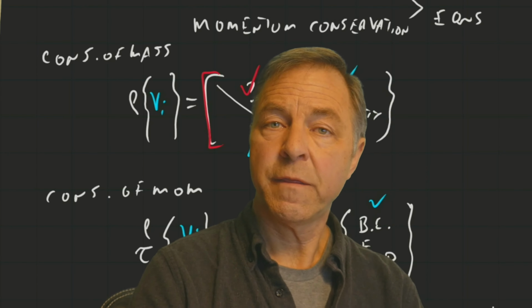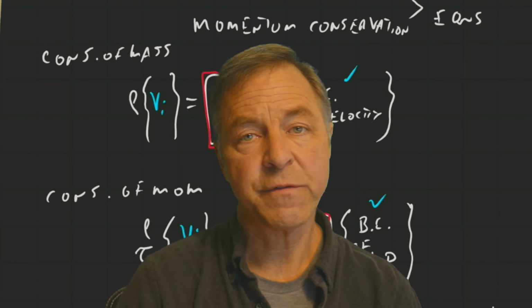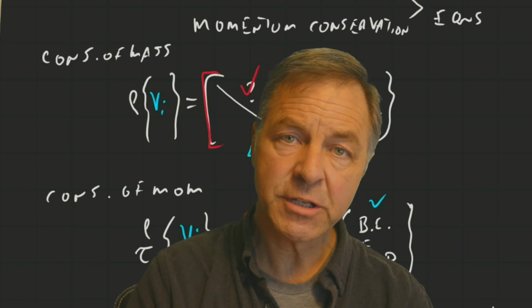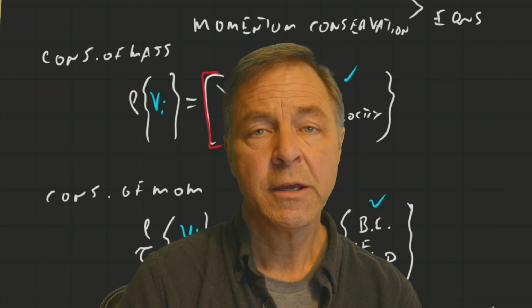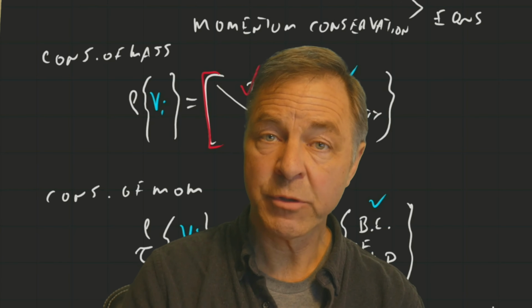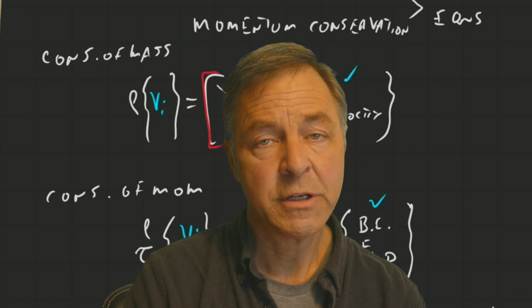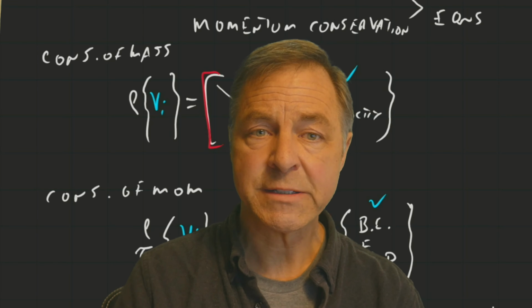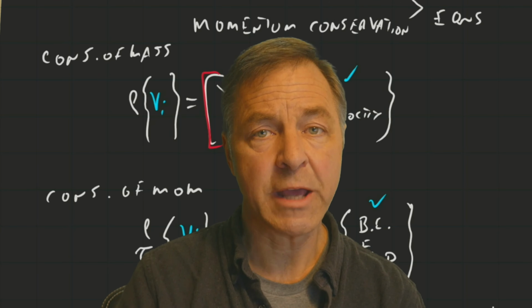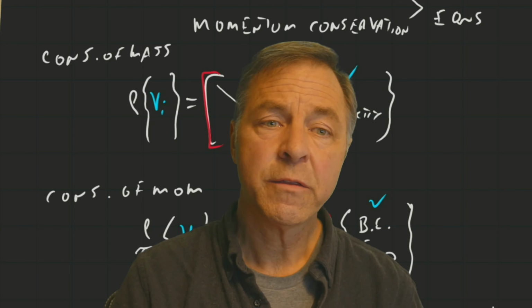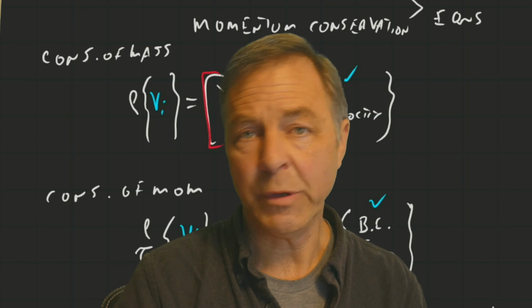So that's important. We've refined the grid size, especially close to the boundary layer where all the action is happening, frankly. In the case of an airfoil, the boundary layer is what creates the lift. So we need to have a grid that allows the modeling of the boundary layer to happen correctly. But then there's also the large-scale bulk flow that we can't ignore.